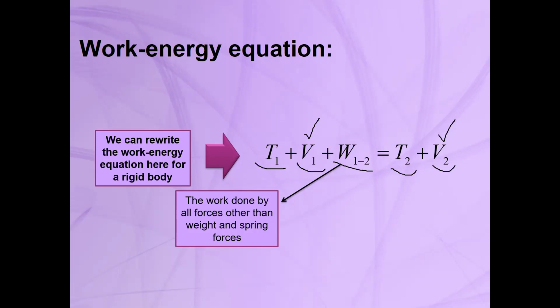We had one question in assignment 1. In the first question, most of you used the work and energy equation to obtain the velocity of that mass before the impact to the ball. But you neglected the weight and this term V. Most of you made the same mistake and neglected the gravity potential energy in this equation.